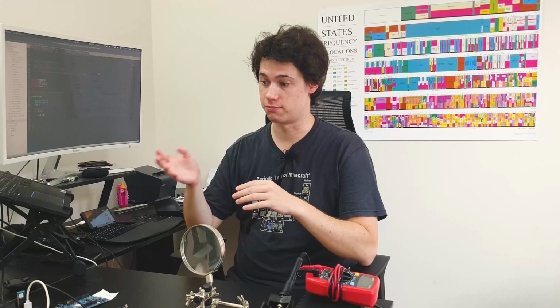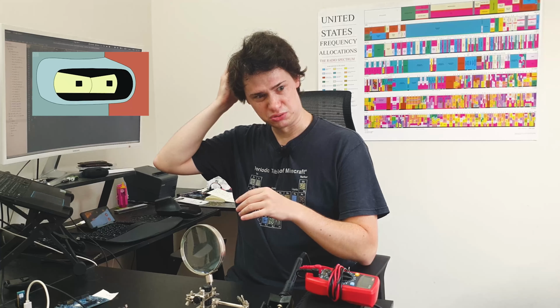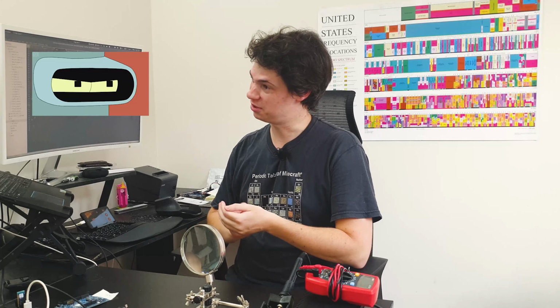The reason why I know that it's gonna create a lot more code is that it's one of my most trustworthy, most reliable tricks for saving space in a microcontroller. In every project, you're gonna have to save space at some point or another because that new feature that you want to implement does not fit. And one of the best tricks in that case is to remove all the floating point calculations. That would work only in a microcontroller that does not have an FPU.